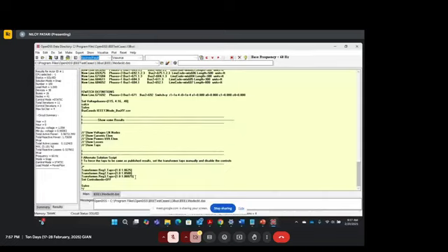Because these are voltage controllers, this regulator is a device which boosts up or boosts down the voltage, so it controls voltage throughout the feeder. Now if the taps are not similar, then you won't get the same amount of voltage throughout the feeder, right? But if the taps are similar and you have the same capacitors present which are on in both the models, then your models should match, right?